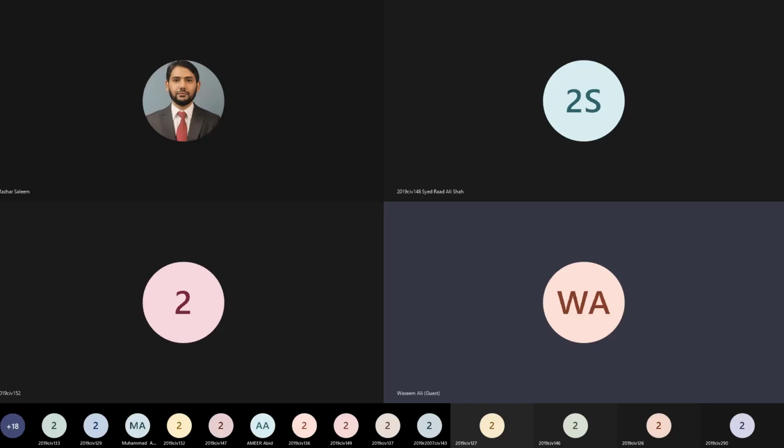I want you guys to check that by yourself, right now or later on, that the small scale reading in the second image of the extensometer is 117. And 117 will be further multiplied with the least count, 0.001. And finally, you will get a reading of 3.117 millimeters. So I want you guys to check that out by yourself. And if you have any problem with that, we can talk about it in the next class. Okay.